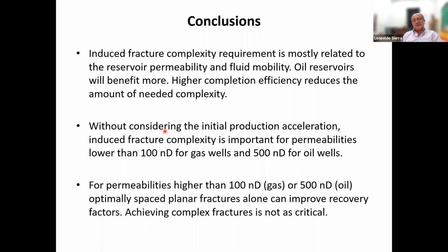This means that, whether you're dealing with unconventional gas producers or liquid producers, the optimum fracture spacing for a liquid producer reservoir needs to be at least 50% of the calculated fracture spacing for a gas producer reservoir.